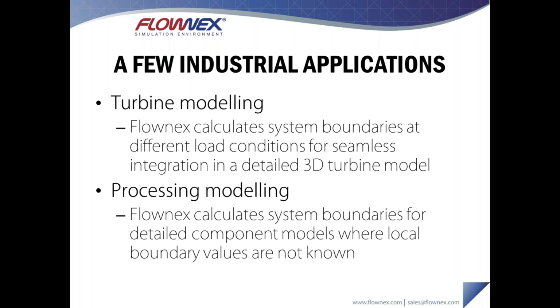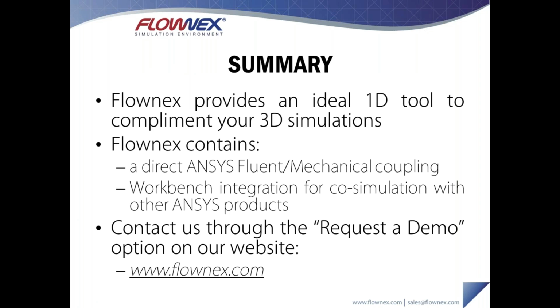This also extends into many other applications in the processing industries, where once again you're looking to simulate the conditions inside of a container or some kind of vessel, or perhaps some kind of processing environment. But once again, the boundary conditions at that container interface are not available due to the difficulty of measuring at that point. Here we can then build a simple Flownex model which can transfer the information from a known point in our plant through the components between that point and our vessel that we're looking to model, and then seamlessly transfer that information to something like Fluent for use in the 3D simulation investigation.